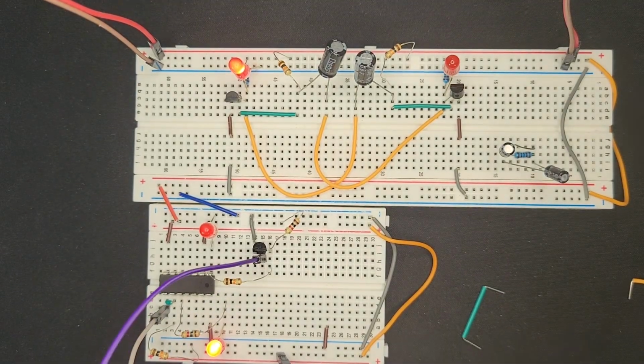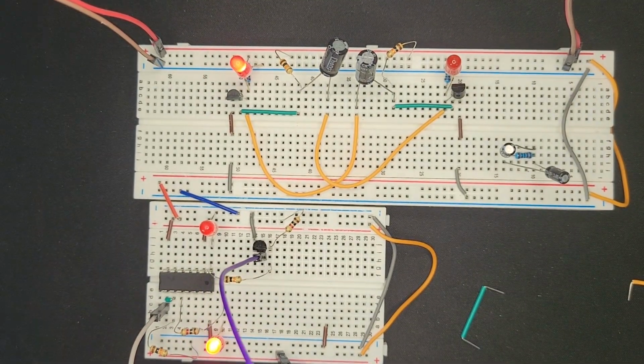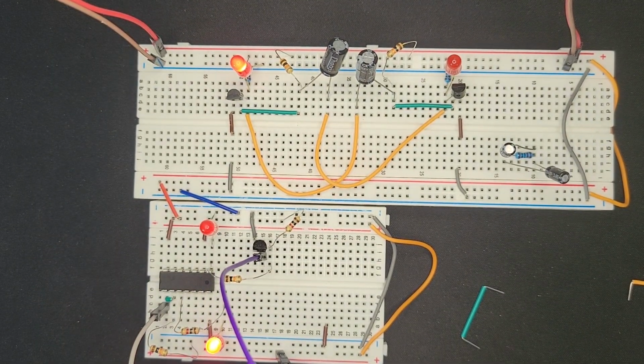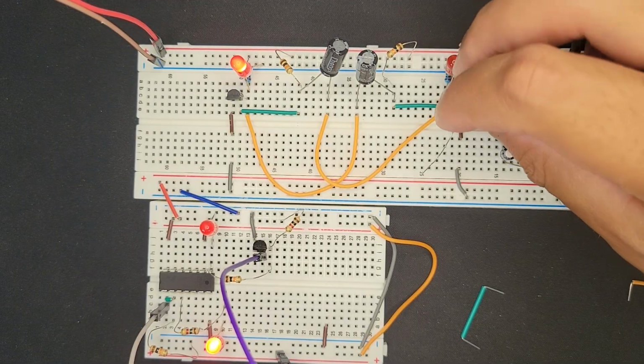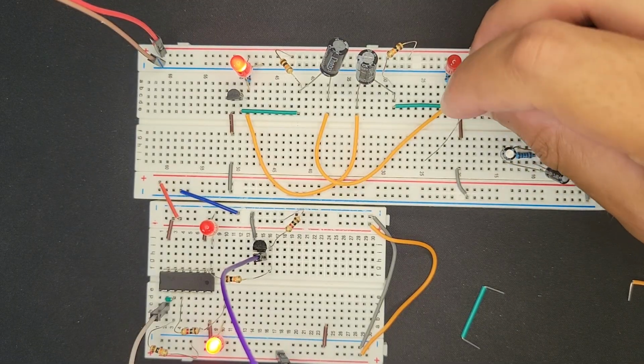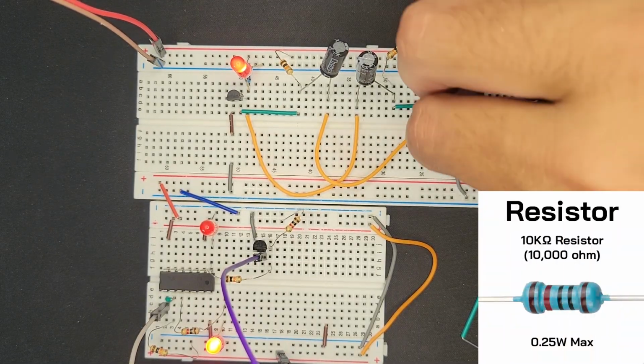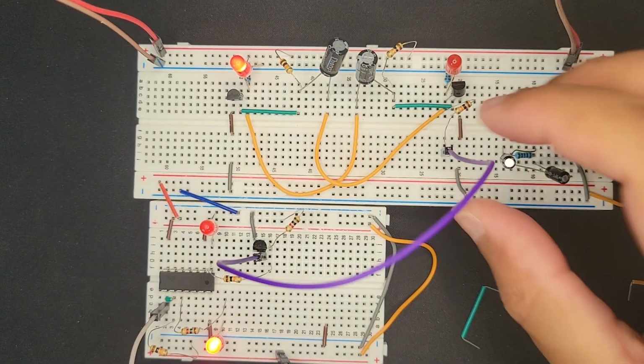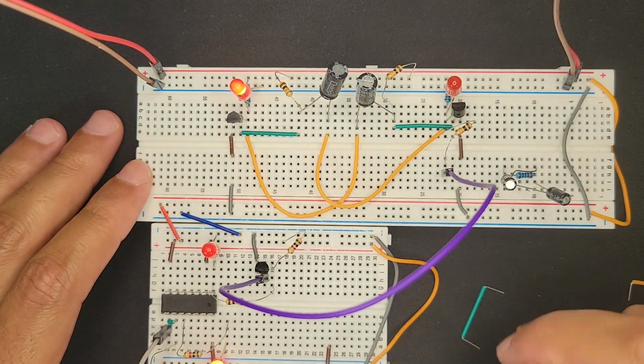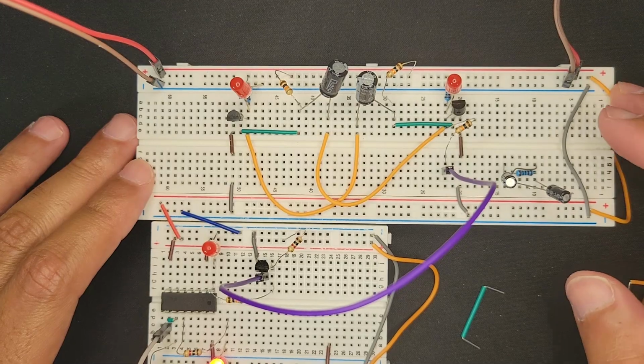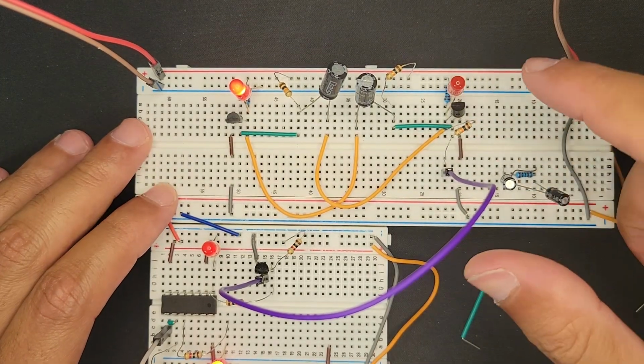So maybe I need to use some resistance, because ideally I'll just get a really small signal. So instead of plugging it straight into the output in parallel, I'm going to use a 10K and bridge it over this gap and then plug that in here and see if that makes a difference. So the multivibrator is still not doing what it was before. What is happening? This guy does not turn on anymore.